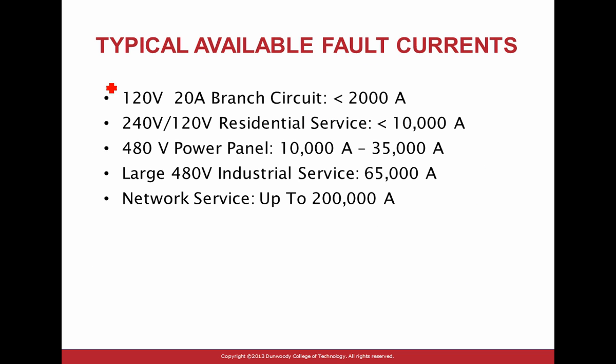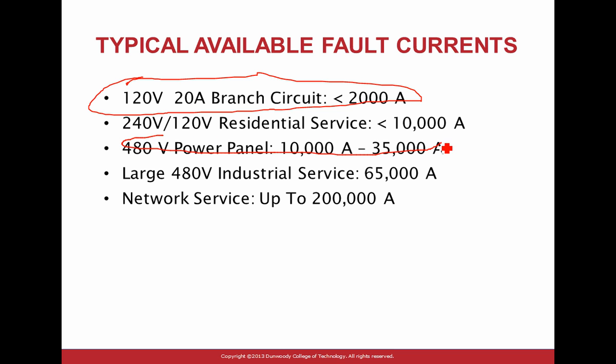So where you are, if you're dealing with a 120 control circuit, you guys are within 2000 amp short circuit, very little. If you're inside a 480 panel, you don't do residential, but if you are, you're at a higher short circuit. So for you guys, where you work on the control circuit will be 2000 amps or less, which is less amps, a smaller ball of fire coming out of it.